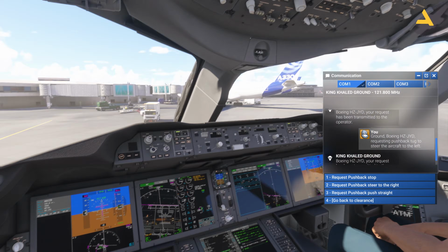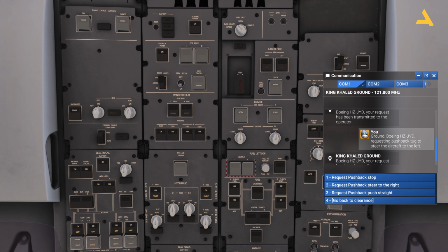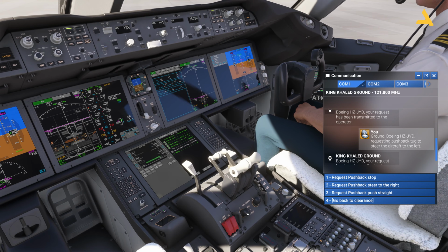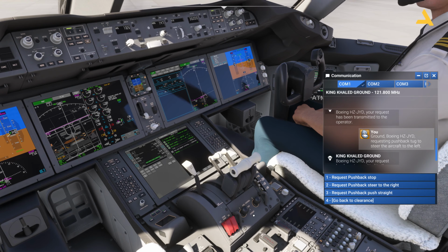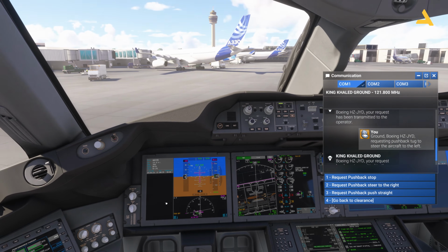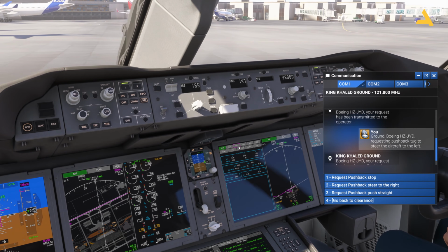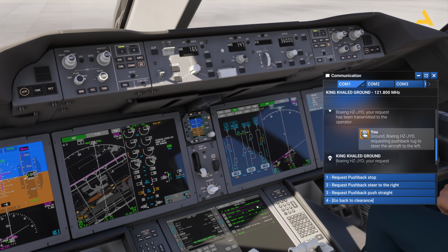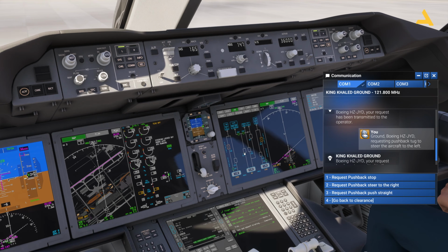That's it. Now you can turn on the engines. So you see the switch over here for the engine. So let's start the engine. You can just start both of the engines at the same time for this plane. And now this is the fuel control switch for the left engine and for the right engine. Now, as the engines will be available, the hydraulic systems will also work. And then you can adjust the trim and then you can carry out the flight control test.